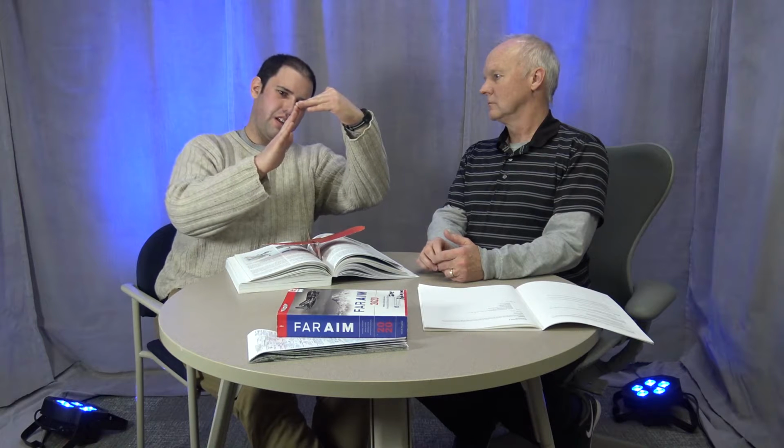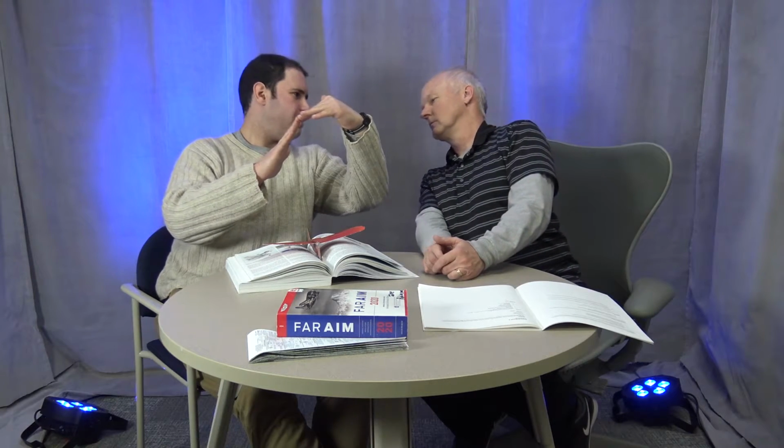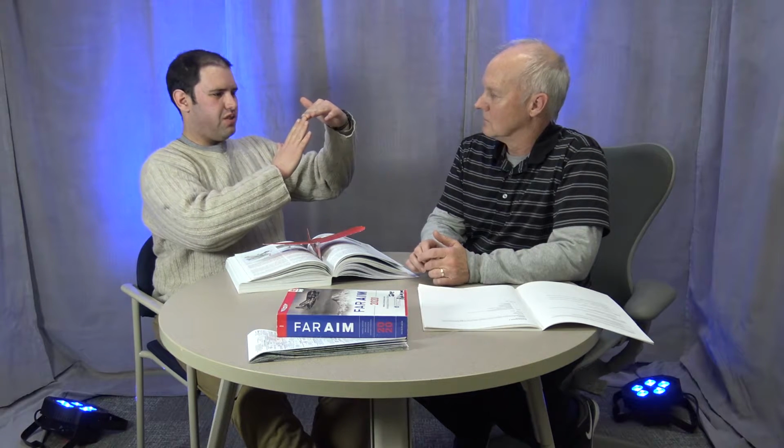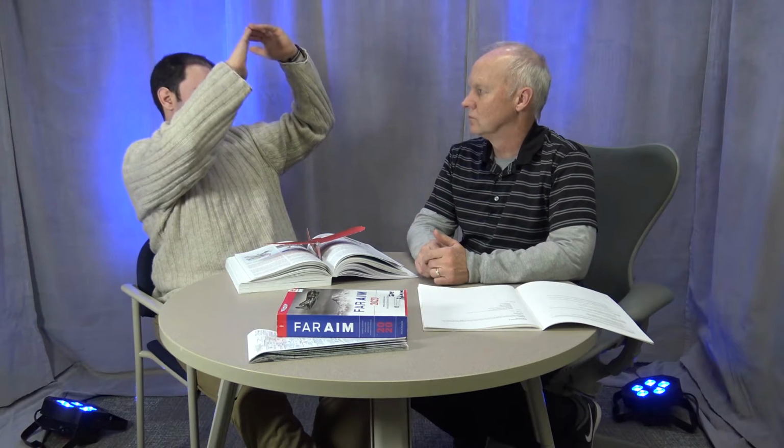So if the angle of attack of the wing is, say, maybe 5 degrees, now we deflect the aileron downwards. Now if you draw a line from the leading edge to the trailing edge, even though the wing itself may be at 5 degrees, the average may be 6 or 7 now, because the aileron is deflected downwards at a higher angle, so the average of the wing and the aileron together is more. And that creates more angle of attack, more lift on that wing, and that wing goes up. If you deflect the aileron up, now the average is less than the angle of attack of the wing as a whole. Less angle of attack creates less lift, and the wing goes down.